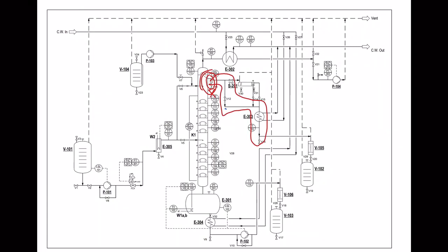Then for the second option, which is at this part, you place a beaker below valve V16 and then go to your control panel, set the reflux divider to position 1, which is total distillate, and then open valve V12, then V16. Then after you collect enough sample, close back valves V12 and V16.